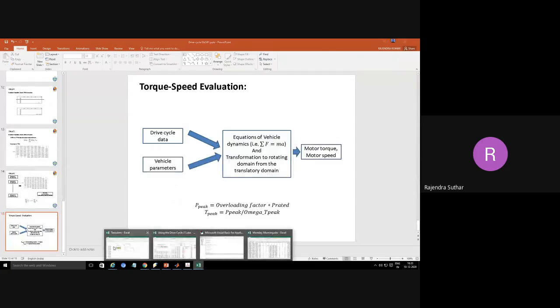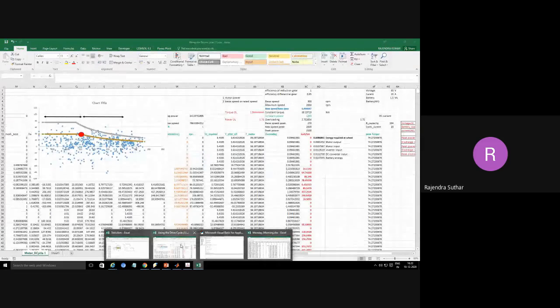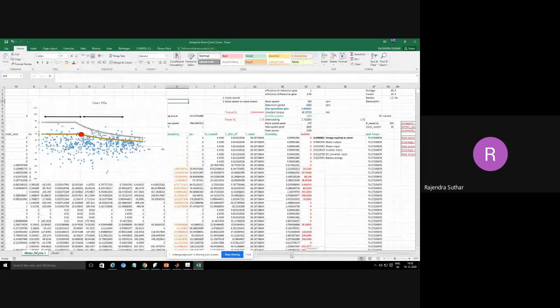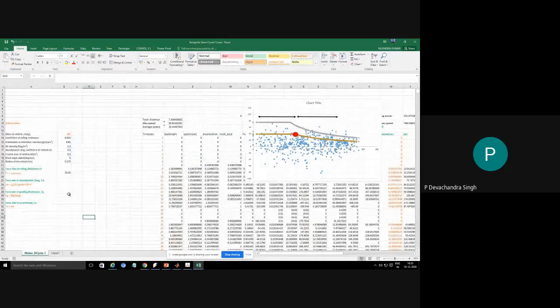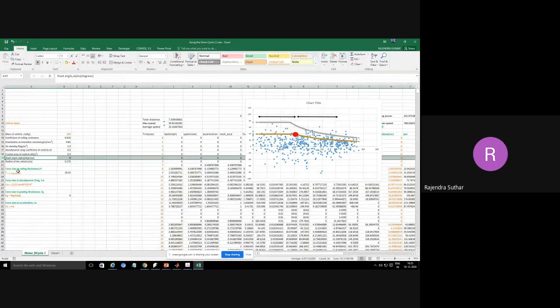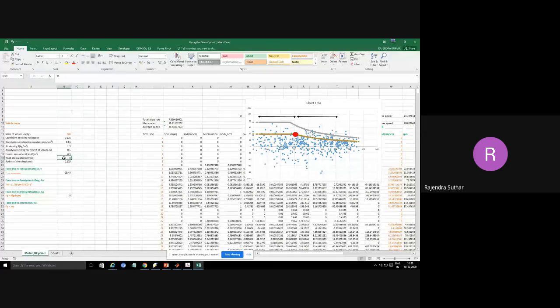Because you may see the sheet which I have shown here. In this sheet, what is missing is this. You may see the grade road angle in this 19th entry. This road angle is zero. Okay, so we can make this road angle 5 degree, 6 degree, but it is not always possible that this road angle is constant throughout this run. It goes on changing.